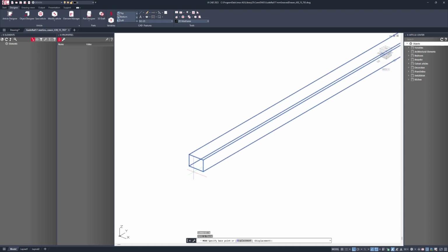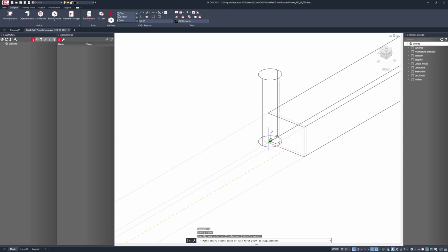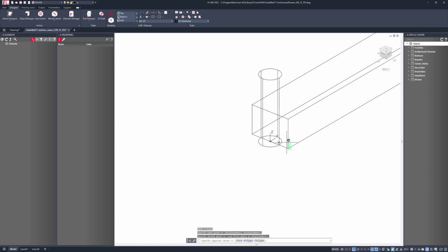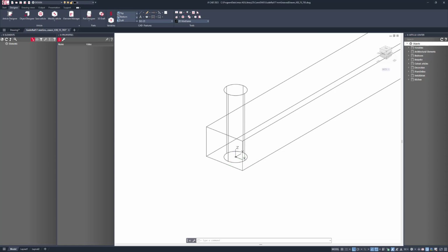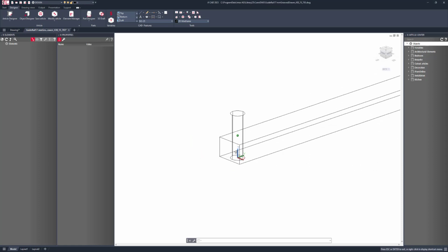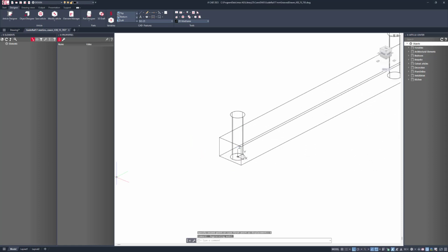And then what I can do is just move this now to that midpoint, and then move it back this way and say that this is 6 mil from the reference geometry in this direction. Let me just confirm that. Where is it? Yeah, there we go, 6 mil. Okay, so now that I have this, I just need to move that dimension down. Oh, and that's 7.5.